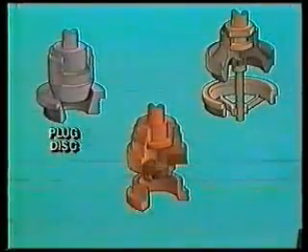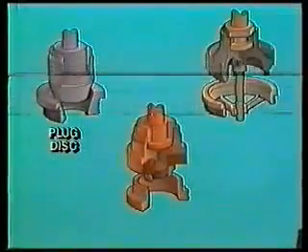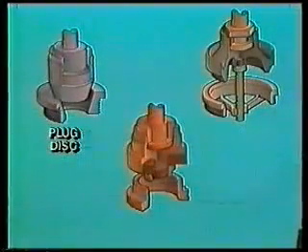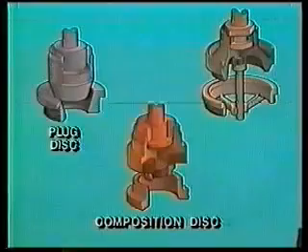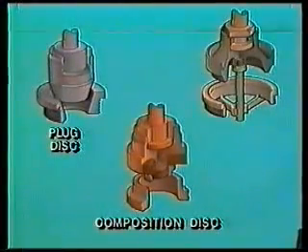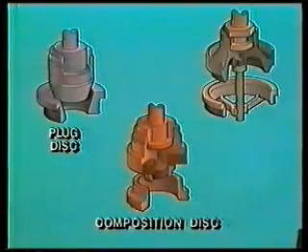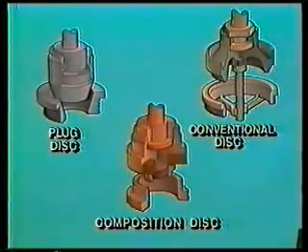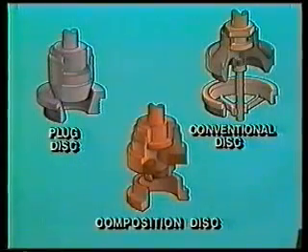The plug disc is the most common globe valve disc, and it comes in a variety of styles depending on its service. Composition discs are made of a flexible rubber-like material so that hard particles from the flow will not prevent a tight closing. Conventional discs are constructed of hard materials like metal or ceramics. Contact between the two hard surfaces will often break up particles deposited by the flow.